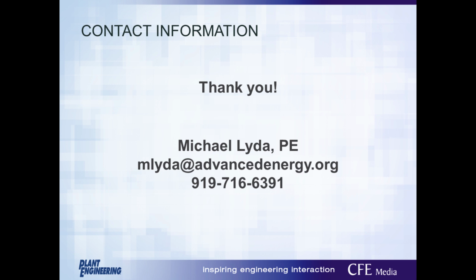We do have a few questions here that we could probably get through real quick. Michael, is air conditioning required for proper operation of a VFD? Just like motors, the ambient temperature in the room, wherever your VFD is held, is going to be important. So just respect the ambient temperature that's on your VFD nameplate and make sure you're not exceeding that room temp where the VFD is stored.